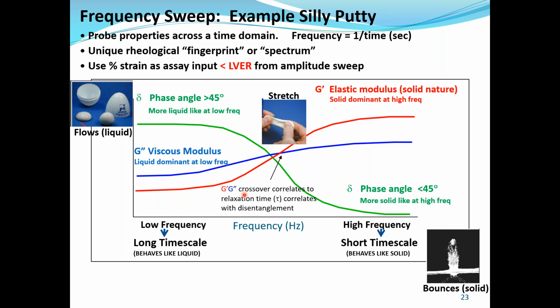Again, it's that linear viscoelastic region. That's the upper limit, so you need to be well below that. So let's look at the rheology of silly putty. If you take silly putty, roll it into a ball, leave it on a table, and come back a few minutes later, you will see that it's changed shape. It is flowing. It's acting like a liquid. Sitting on a table is a low frequency event, a long time scale.